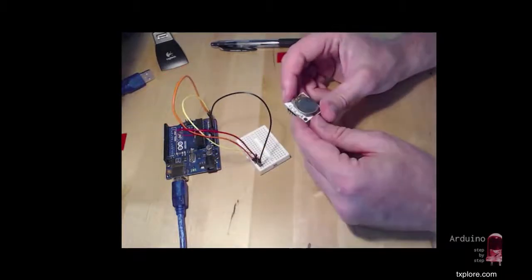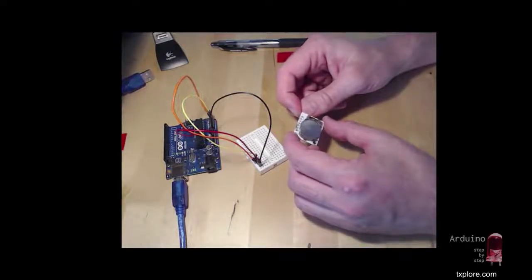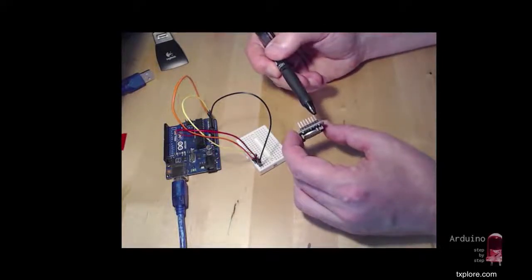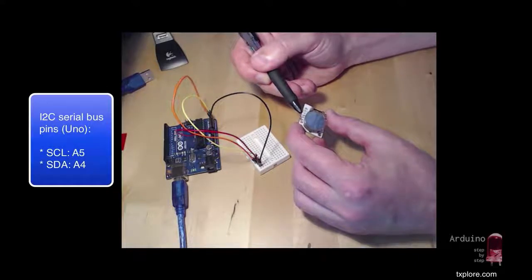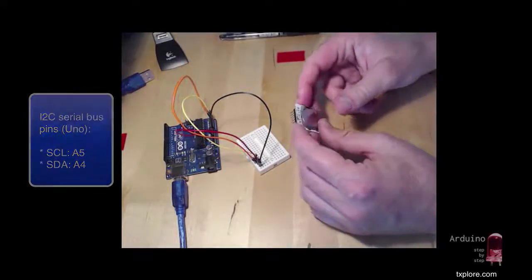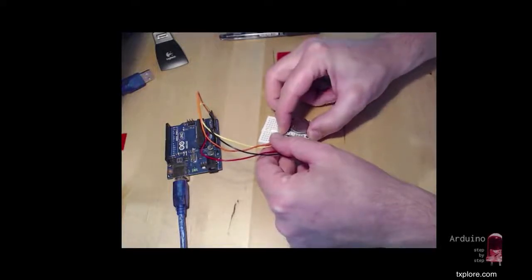A couple of things before I plug it in: the PCB communicates with the Arduino using the I2C interface, a two-wire interface. I have soldered the header onto this row of pins, and the pins that I'll be using are the serial clock SCL pin, then there's the data pin, and then there are two power pins, ground and 5 volts. I've already done the wiring on my mini breadboard, so I'm just going to plug it in.